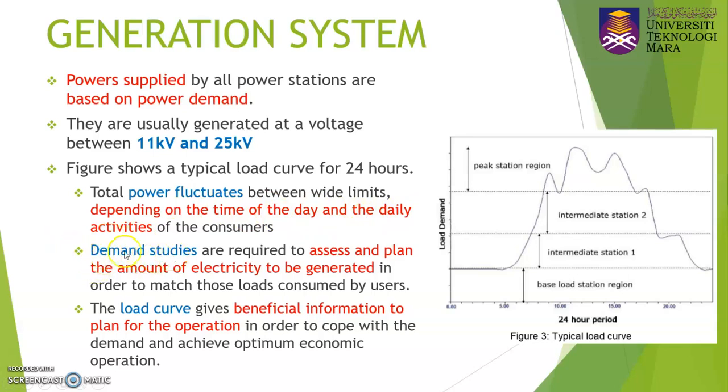The demand study is very important in order to assess and plan the amount of electricity that needs to be generated to match the load demand. This load curve gives beneficial information to plan the operation in order to cope with the demand and achieve optimum economic operation. Based on this, we will know which power station needs to be turned on and operated in order to meet the load demand from the end user.